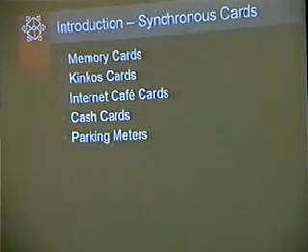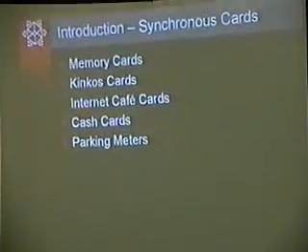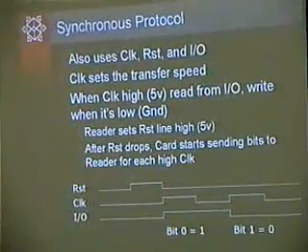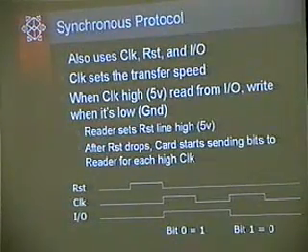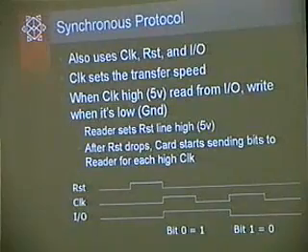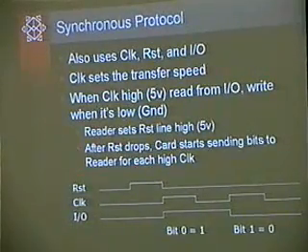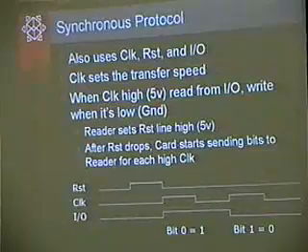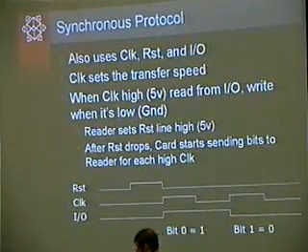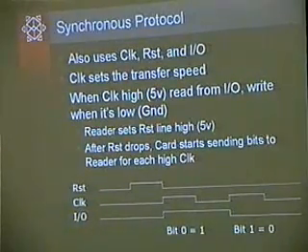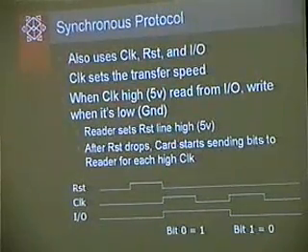These cards are synchronous smart cards, and they're just like memory cards, just like Kinko's cards, Internet Cafe cards, cash cards. And the synchronous protocol is very, very simple. The clock sets the transfer speed, and so the reader just kind of moves the clock up and down from 5 volts to 0, and uses that to create the clock for the actual card. And if the reader wants to start reading information, it just sets the reset high to tell the card to reset, and then starts ticking the clock.